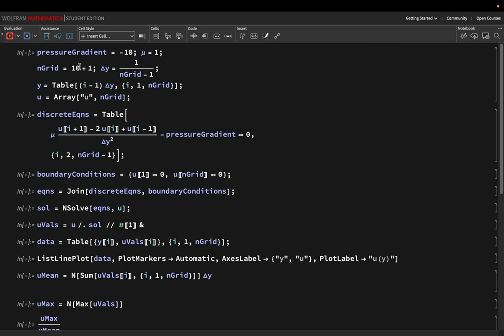So just like before, you take the number of grid points, pressure gradient, whatever value specified in the problem. So your discrete equation is mu into (u_i+1 minus 2 u_i plus u_i-1) by delta y square plus the pressure gradient term. I have put minus here because we have minus del p del x. If this is minus, then it means the pressure is actually increasing as you go along the x, then the velocity will be positive. If it is a positive pressure gradient, which means pressure is increasing along that direction, then the flow will actually be reversed.